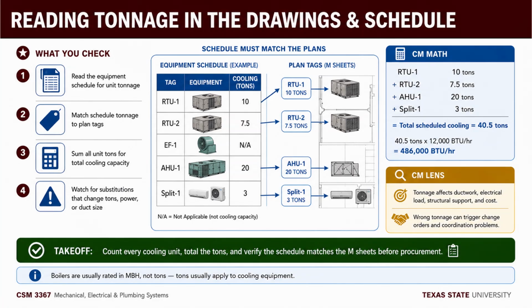In summer, the sun rides high at midday, so it strikes south glass at a steep, glancing angle and much of it bounces off. South glass is also the easiest to shade. A modest horizontal overhang kills the high summer sun and still lets the low winter sun in. South is the designable orientation.